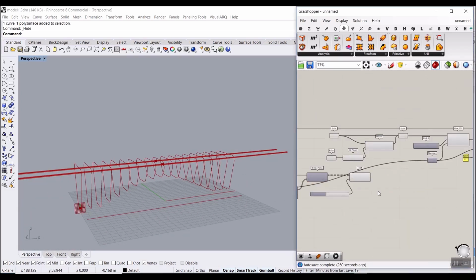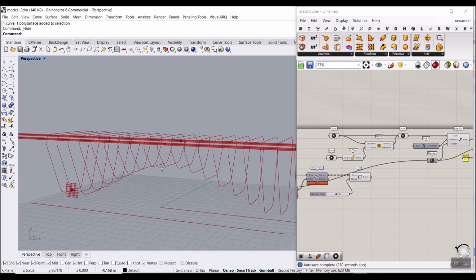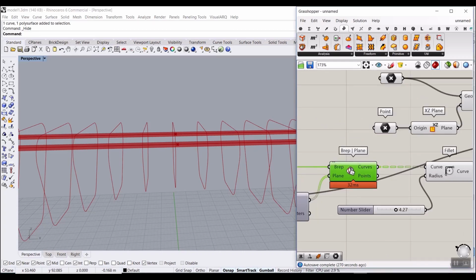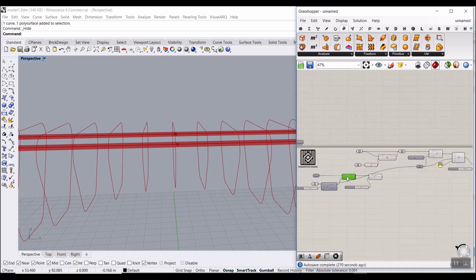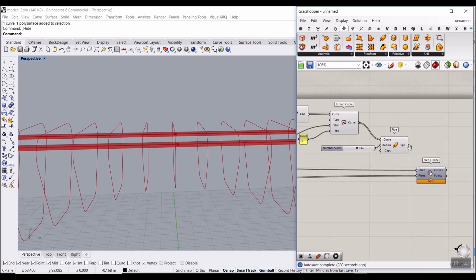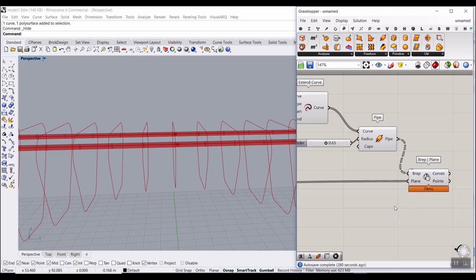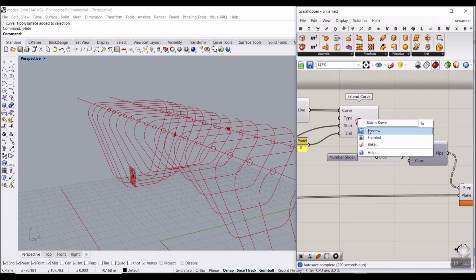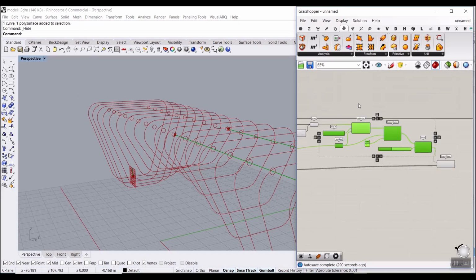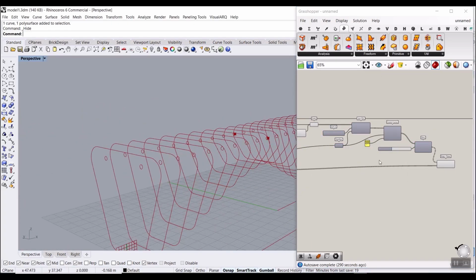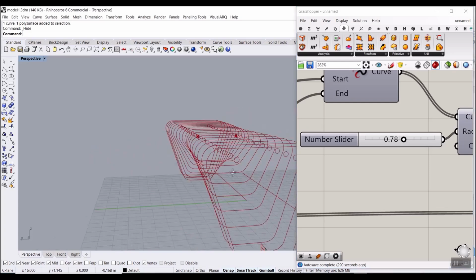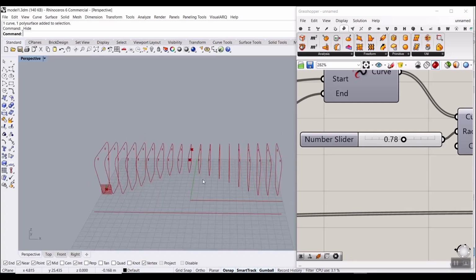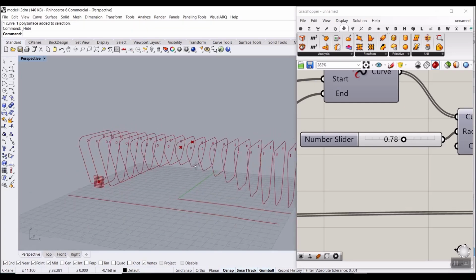And now when we have the pipe, we have to also find the intersection of this pipe with these planes. So it's going to be obviously like this. Let's just copy this, Control C, Control V, bring it forward, and give this to the pipes. Turn it on. You can see beautifully. Let's just turn the pipe off, the extended curve off. You can select all of them and turn it off. And then you can have this, here's the pipes, in all of those sections. That's it. So now we have all of them in the sections we want to make.